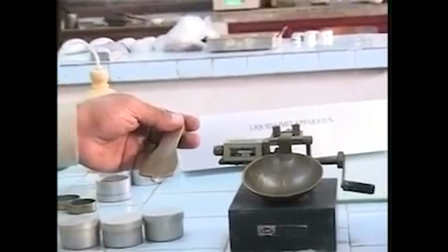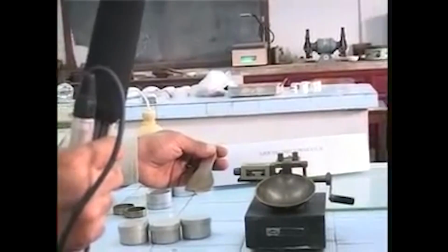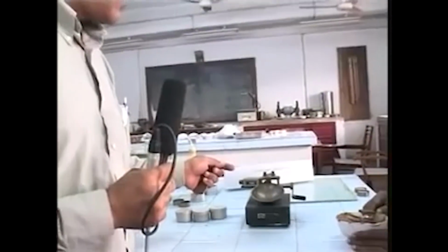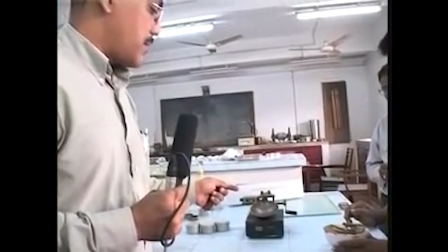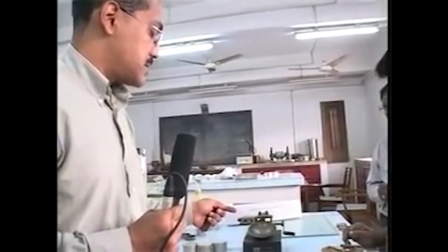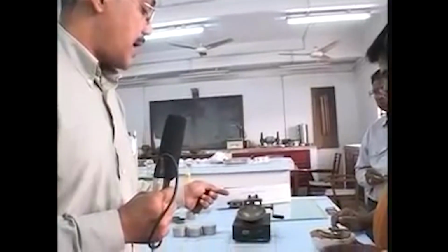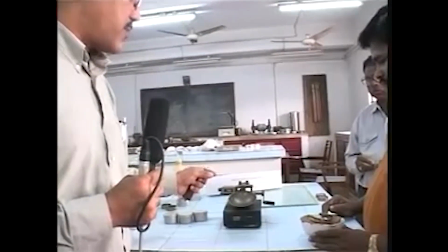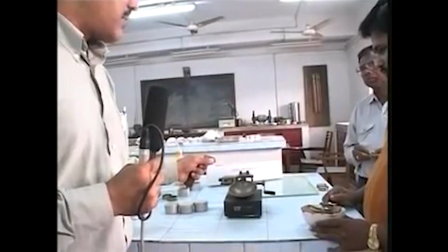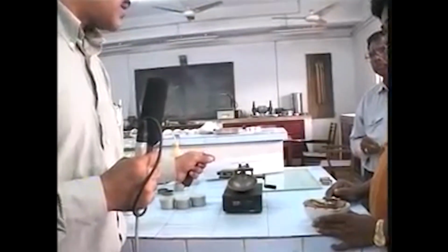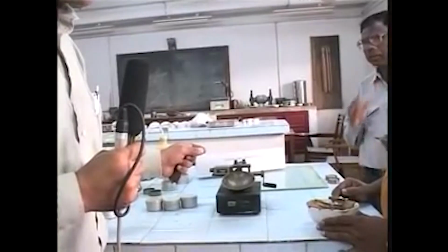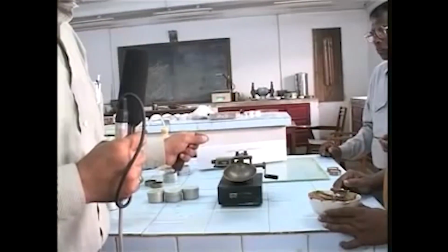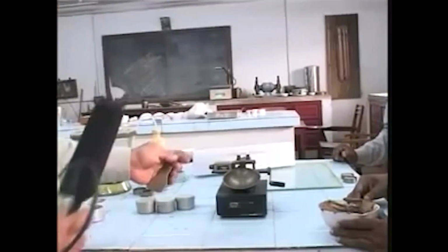You can imagine that as the soil becomes drier, you are going to require more and more blows for closing the groove, and we are going to plot it on a semi-logarithmic scale, and find out the moisture content required for 25 blows closing the groove by 12.5 millimeter. You are going to see that in the next level.